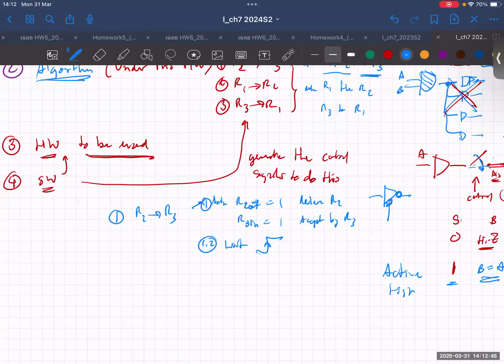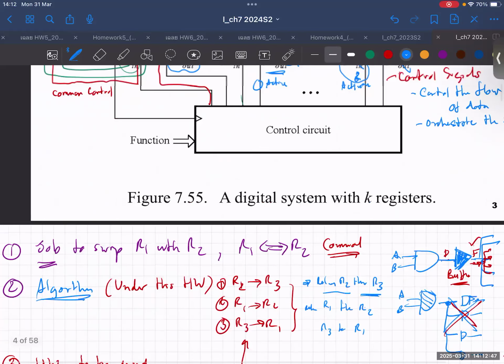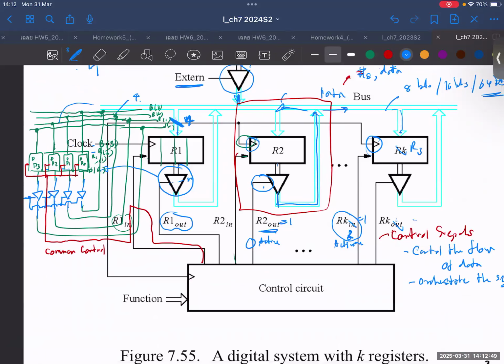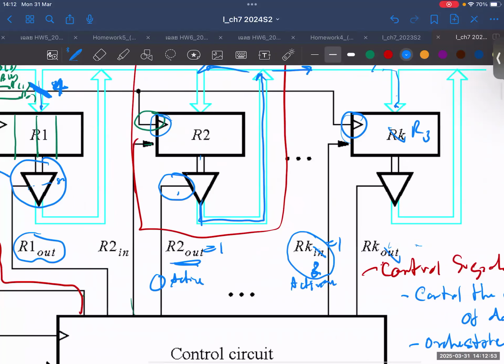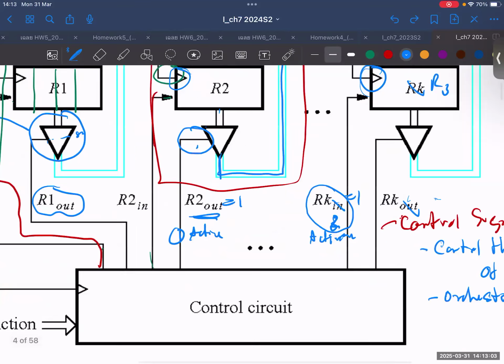And that clock edge is the rising edge, as you can see from the symbols. This is your choice. If you want the falling edge, you just push the bubble there, right? But for this particular example, you decided to use the rising edge. So you have to wait, okay?